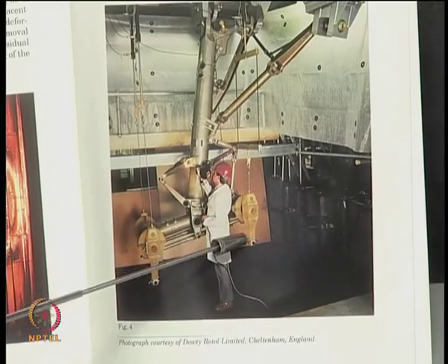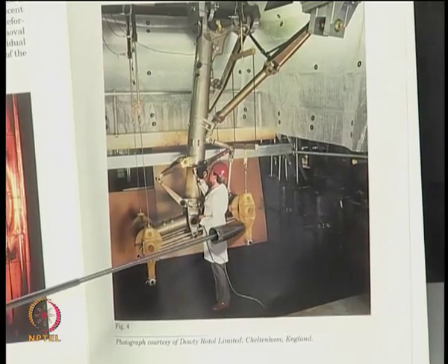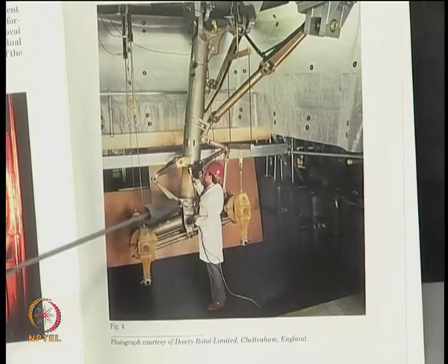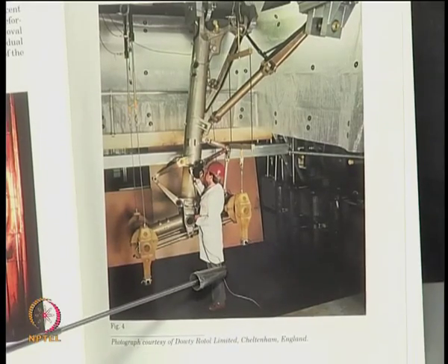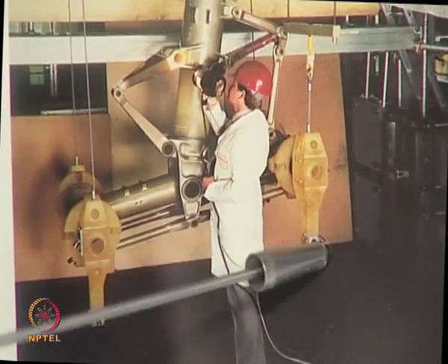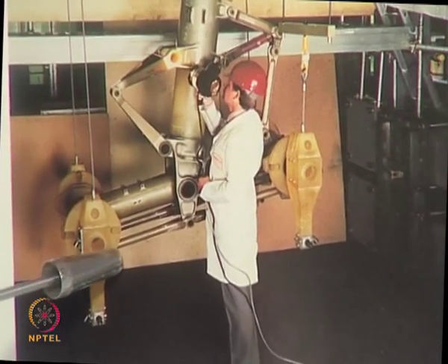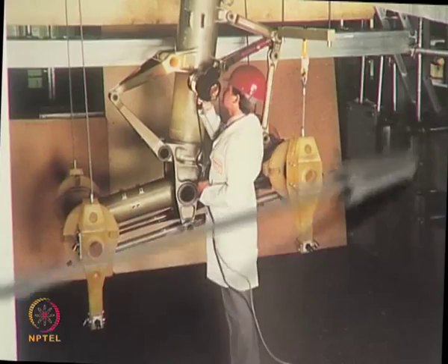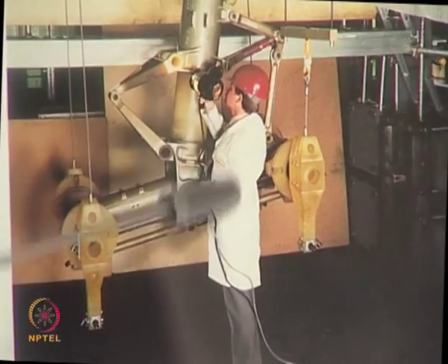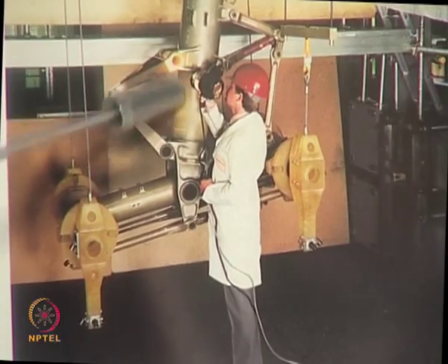In fact, chemical engineers are employed to tame the epoxy material, so that they get the model free of residual stresses when such a huge model is being cast. So, the figure clearly shows that this model is made of epoxy. You can distinguish it from its color. So, the entire model is made of epoxy, that is coated with photoelastic coating, and you can see the individual watching for stress concentration using a reflection polariscope held in his hand.